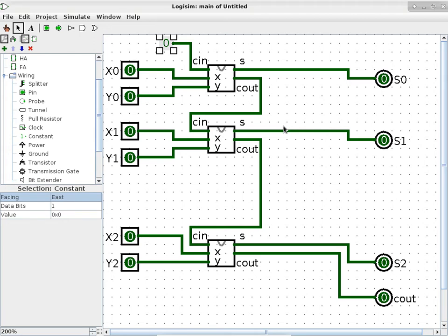This is why we have the carry out having its own bit, and the processor can remember the carry out of the previous addition operation, because you can feed this C out of one addition operation as C in to the next operation. But at this point, I'm just going to assume it's a 0. I'm not going to stack add operations. But there will come a point of time when it is really helpful to be able to stack these things.